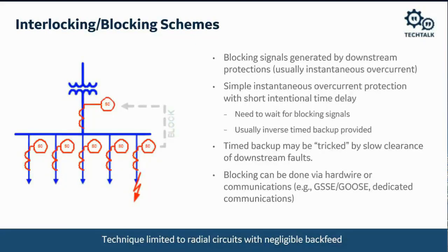Some of the advantages of this scheme: very easy again to implement. We're just using the protection that's already there on the feeder relays and the source relays, so we don't need dedicated CTs. It's simple because all we need is instantaneous overcurrent protection.